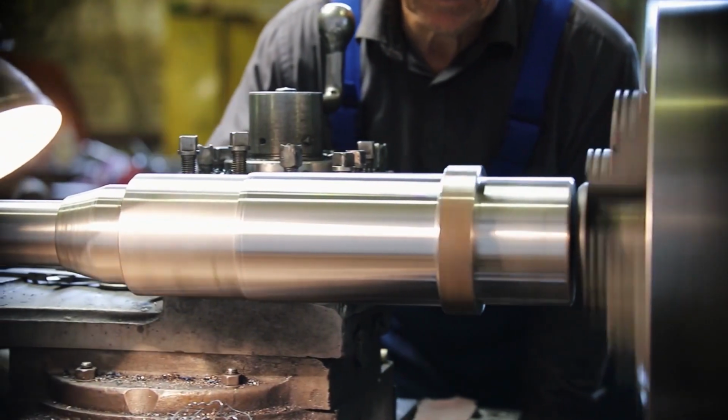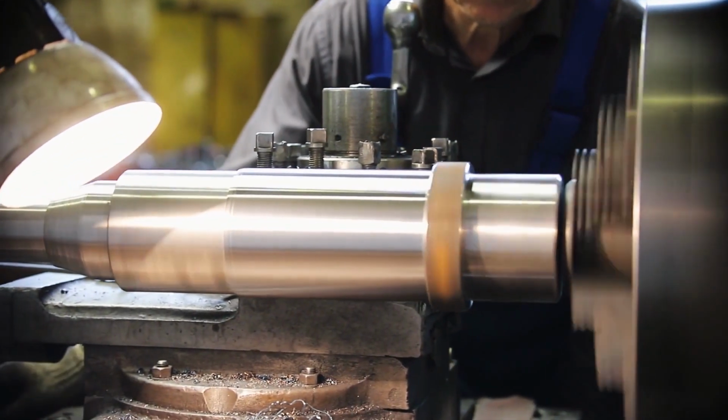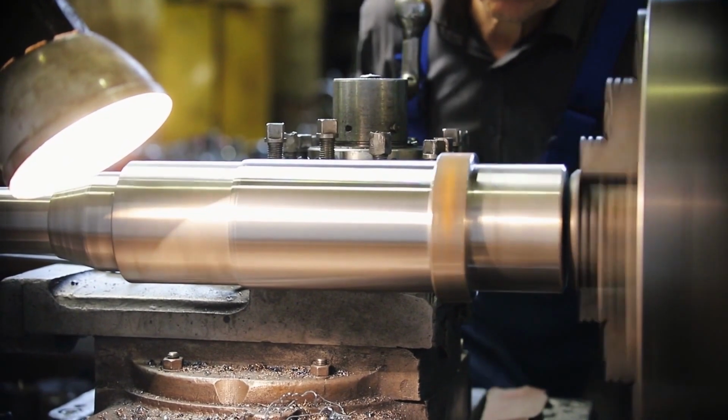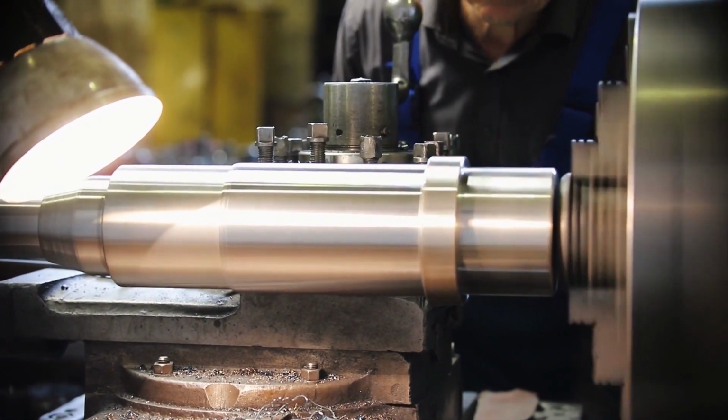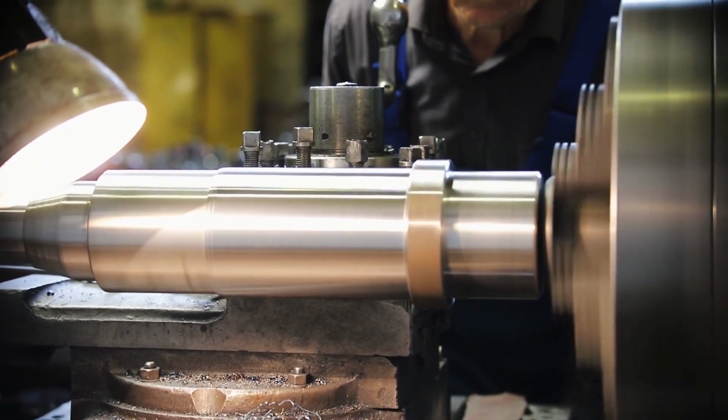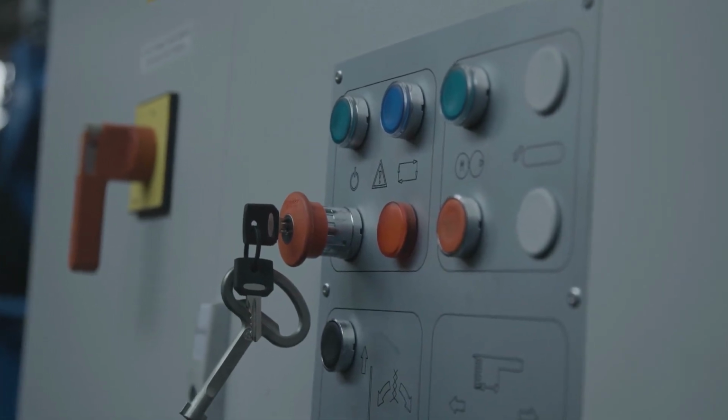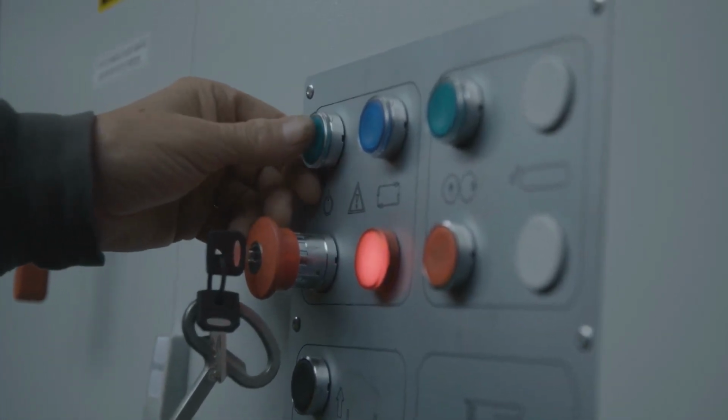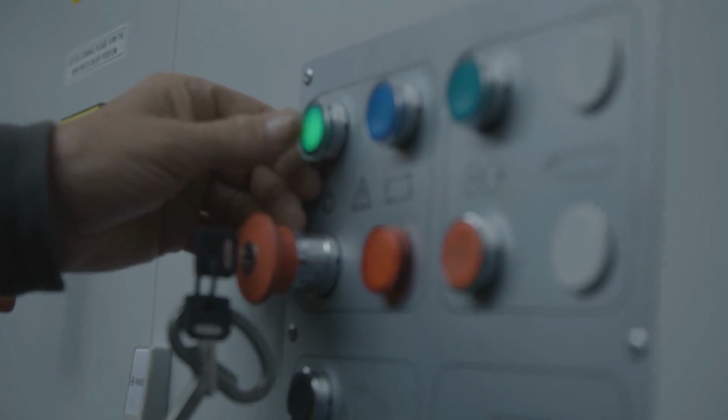A perfect example of how control measures have minimal effect without proper training and adherence to procedure is lockout-tagout. Imagine you are repairing a piece of machinery with internal moving parts. What is preventing someone else from turning the machine on? Did you flip a breaker, unplug the system, or toggle a kill switch? Each of these efforts are easily undone. Simply shutting off machinery isn't enough.